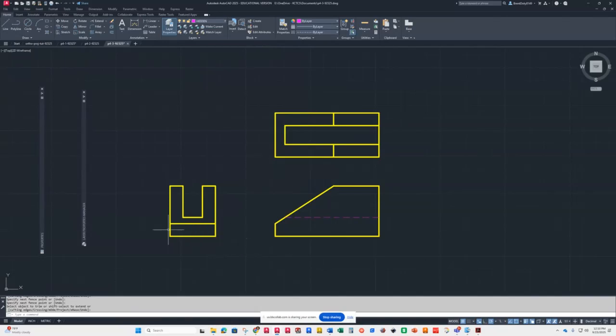So usually what happens is I have people that draw these lines down to here, they leave this line out, they forget to put a hidden line in, or they line it up with the bottom of here. Well, it's at a different height, so it looks like this. And the intersection here should match this line right here.